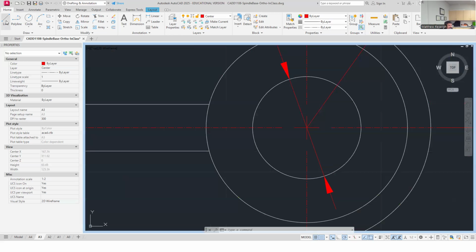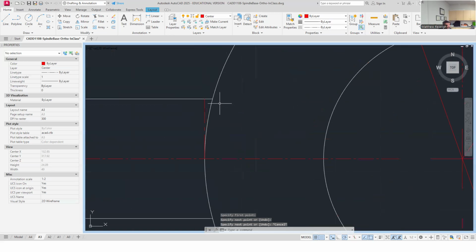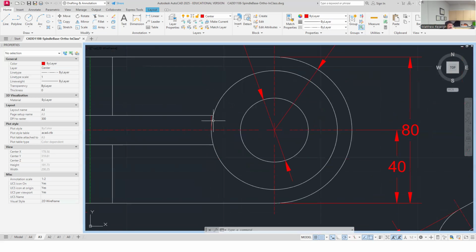So what we're talking about is this difference from here to here, this little amount of material. In order to make this part, you need this material on the part so that you can put this radius in it to make it fit into this cylinder-shaped part. If you only size this part to right here, you end up with a gap here, which might be insignificant, but it could be fairly significant. So you just stuff it with glue or whatever.